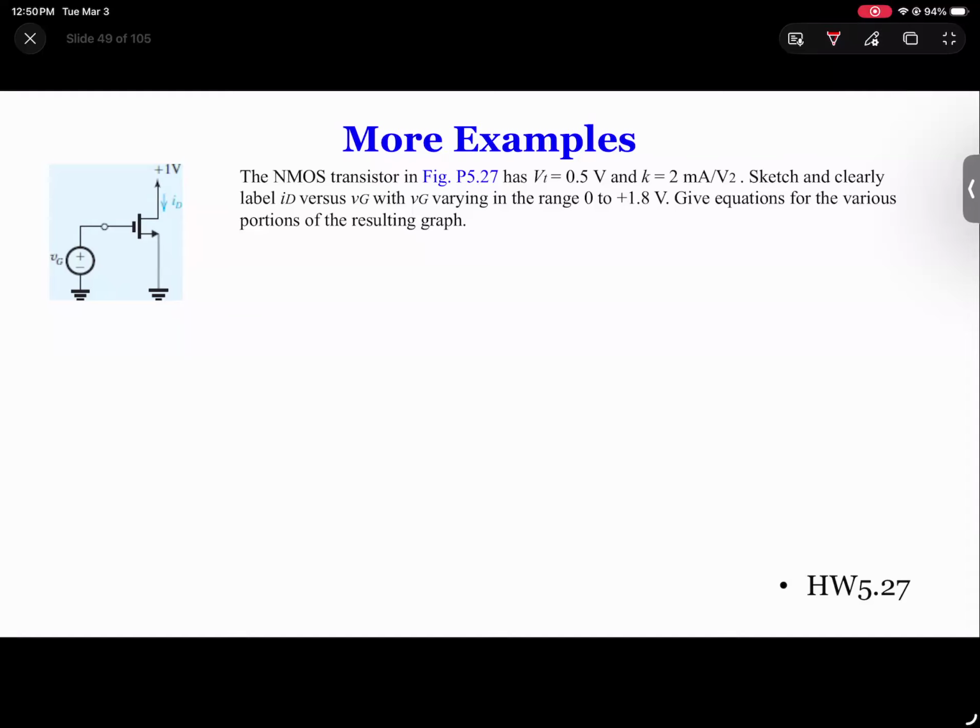But when we move on to chapter 7, of course, we forget about this and we move on to the small signal, totally different. Okay, so now we have an MOS. MOS, we can write down the numbers. So VT is given 0.5, VD is given at 1 volt. So this is D, this is G, this is S. I like to mark them down on the diagram so that later when I look at it, I know exactly what I'm looking for. Sometimes you don't write down, you might just get confused and forget about what you're doing.